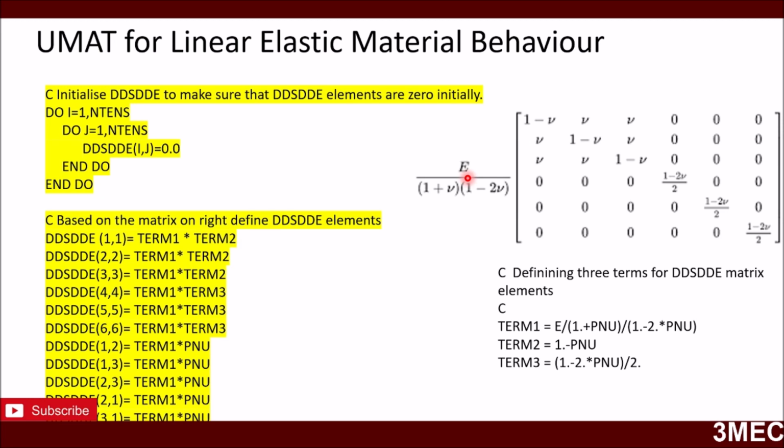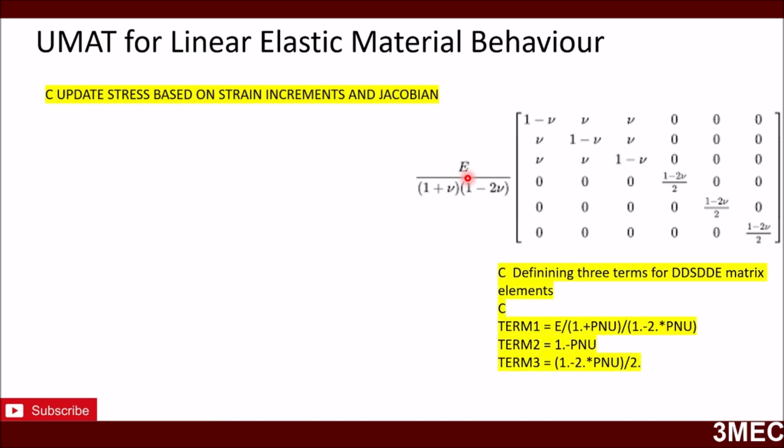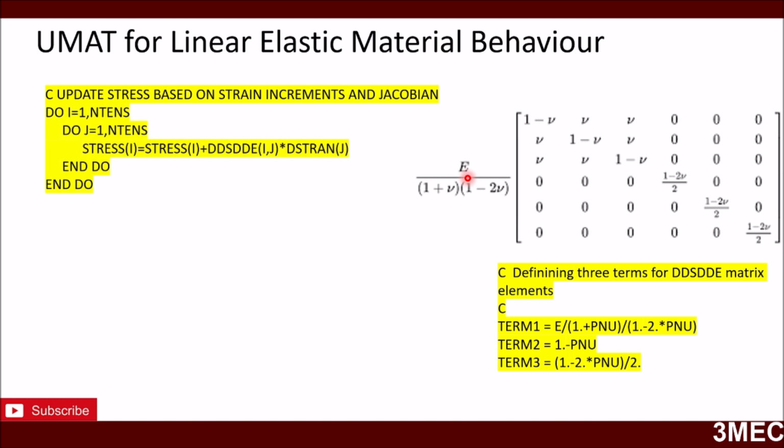Okay, so that's what I have done here, and now I need to update the stresses. I will always do everything in an incremental form, because in later cases when we will be doing elastic plastic analysis or viscoelastic analysis, everything will be time dependent and will also depend on the strain increment. So when UMAT is called, it calls the stress one, and stress basically stores